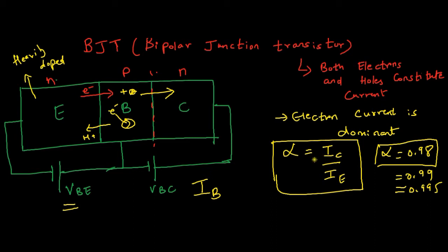So it can be understood from this discussion that if the forward bias across the emitter-base junction is increased, more electrons will leave the emitter and consequently more current results in the base and collector. However, if you increase the reverse bias, say this VBC, from 1.01 volt to 1.5 volts, nothing much happens in terms of current in the BJT.